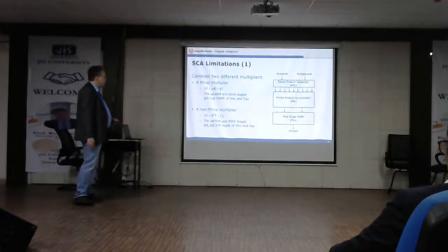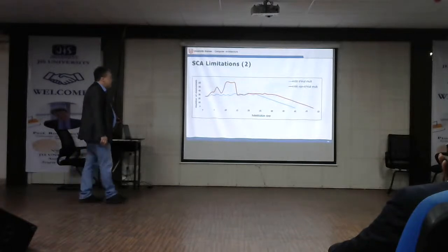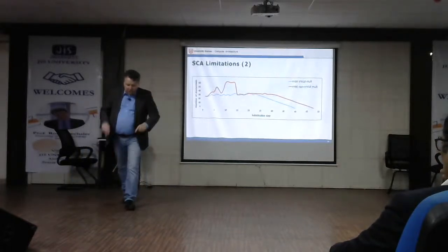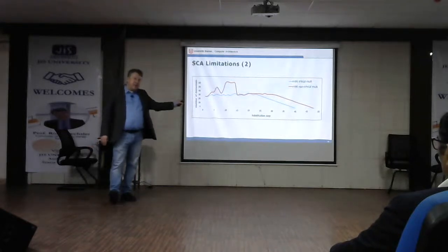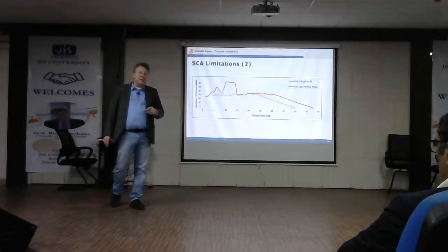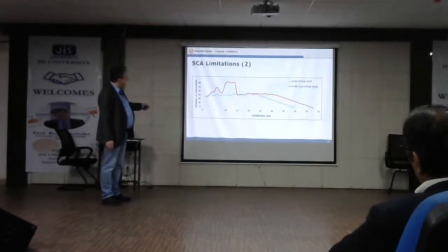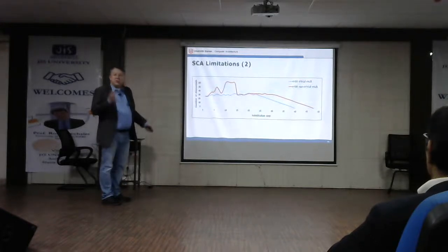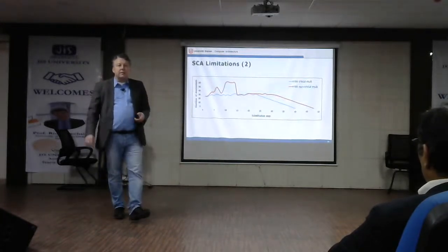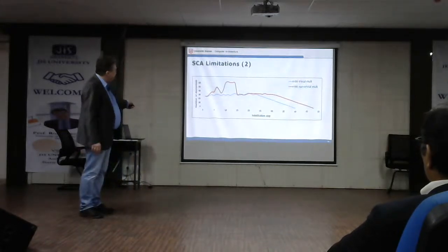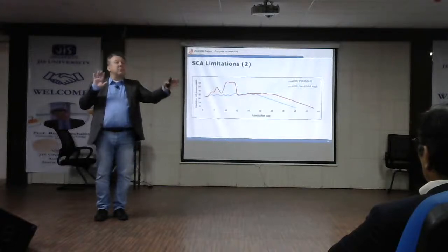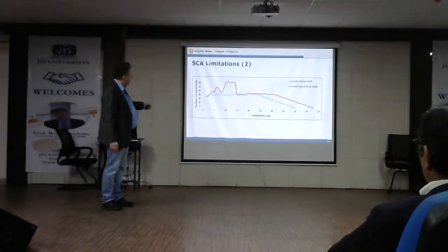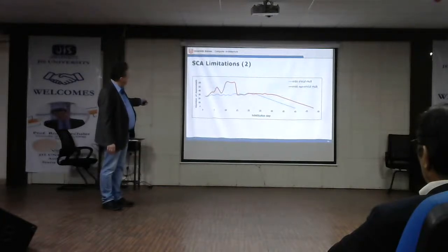Now let's look at this algorithm from an experimental point of view. Before we had a 2-bit multiplier. Now we look at a 4-bit multiplier, and we do exactly this kind of substitution, this backward process, and look at what happens experimentally. Then we see that the trivial multiplier needs almost no memory in between, and finally goes to 0. In the correct case, 0 means this is the correct multiplier. In number of monomials, it needs around 30 terms, and the number of terms corresponds to the memory requirement in between. The other one needs almost twice as much, something like 60 terms.